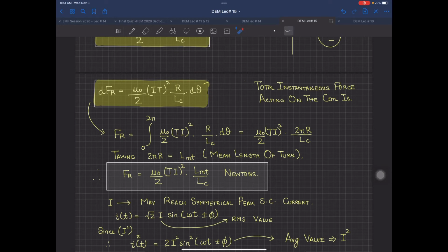trip it. What I mean by this is, we know whenever the fault occurs at this point, at the peak, what happens? The current will go to an extreme value and then come down, and then you will have some decaying component over there. Depending upon the case. Now, when I have this one, you have to cut it off at the peak or even before the peak so that it dies down. Because if that current reaches the peak value, the transformer is gone. Transformer is certainly gone. You can't even brace itself for safety.